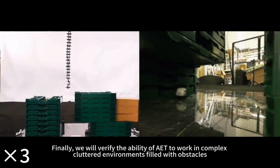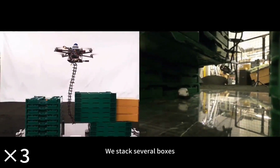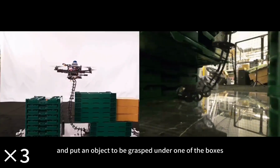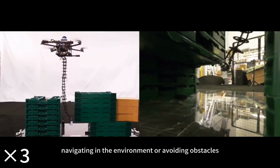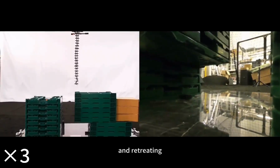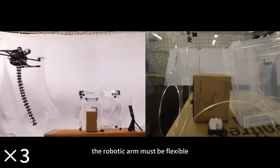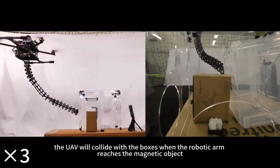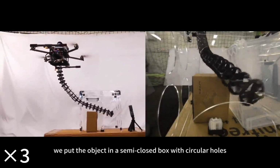Finally, we will verify the ability of AET to work in complex cluttered environments filled with obstacles. We stack several boxes, leave a vertical gap, and put an object to be grasped under one of the boxes. The whole process can be divided into 4 steps: entering the environment, navigating in the environment or avoiding obstacles, interacting with the object, and retreating to successfully pass the gap and grasp the object. The robotic arm must be flexible, otherwise, the UAV will collide with the boxes when the robotic arm reaches the magnetic object.